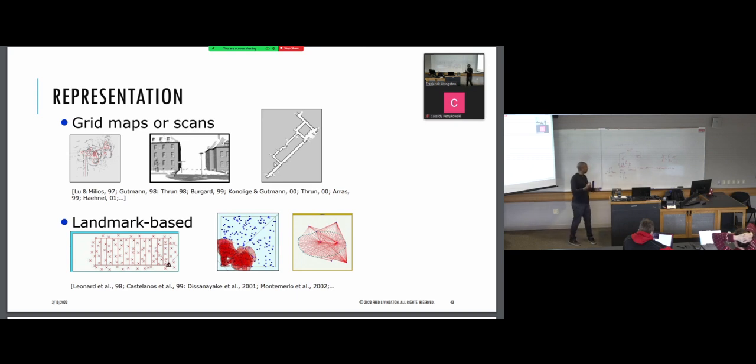That's one of the parameters you need to adjust to make the algorithm run better, though it's slower. Everybody's probably going to use SLAM, but fine-tuning the grid size is going to make it react differently. So I could have a grid like this, or it could be huge, or it could be really tiny. Those are the things about making the algorithm run better or not.